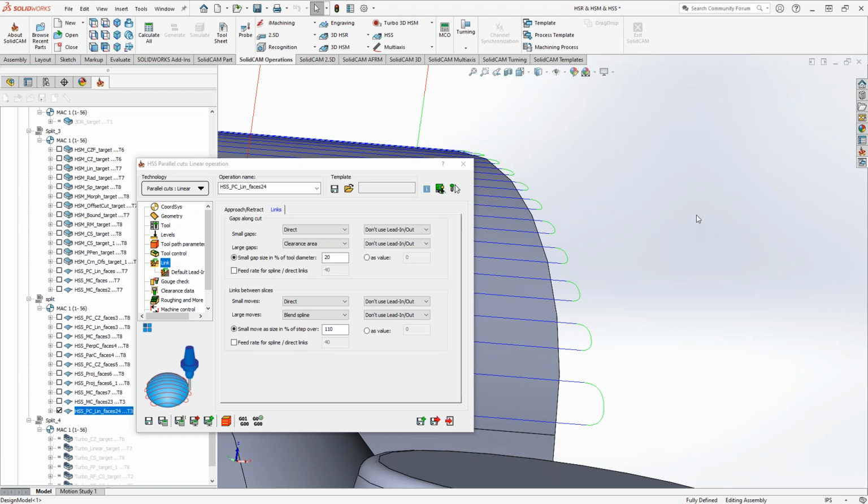That's kind of why it's called the blend spline, because it's blending it through, creating that spline in there of that arc. So now if Mark had another surface that was butted up next to that, and we did the tangent or the extension overlap, as well as the blend spline, that tool path intersection point would be nearly invisible.